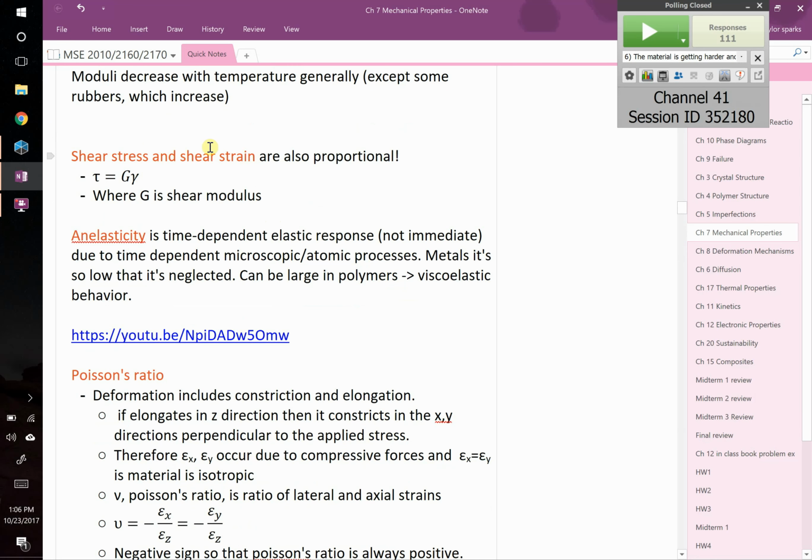Okay, shear stress and shear strain. We talked about shear stress again. If I took this table and pressed straight down on it, I'm applying compressive stress. But if I'm pushing along it, using the friction, while there is a component that's pressing down, there's also a component that's pressing parallel to this face. So I would be shearing this table a little bit. Shear is a different type of stress we talked about in the video on Friday. And just like with stress, if I apply stress and the constant of proportionality is Young's modulus, that tells me how much strain and compression occurs.